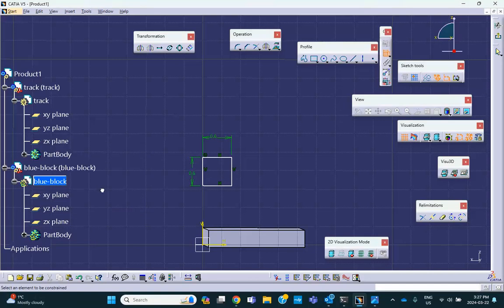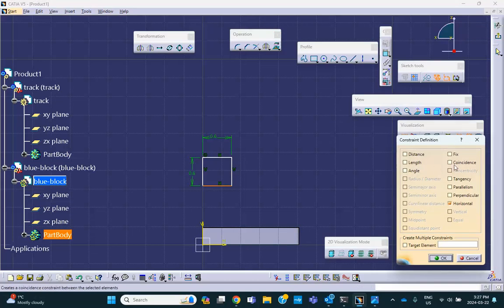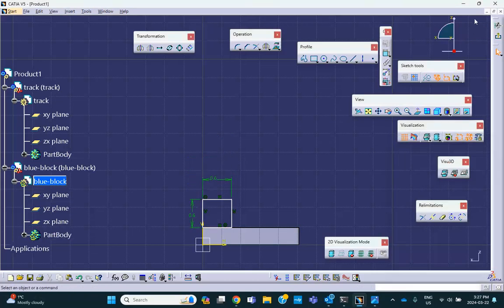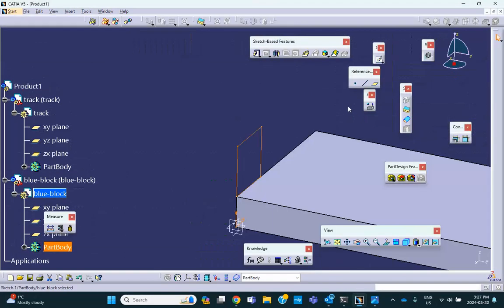Okay, and I'm going to bring it and place it on that top plate. So let me see now. Where's the view? There is the normal view. So for example, I can say this line control that line, and I'm going to make it coincident so that it brings it down and places it on that plane. Exit and pad it by 0.6.